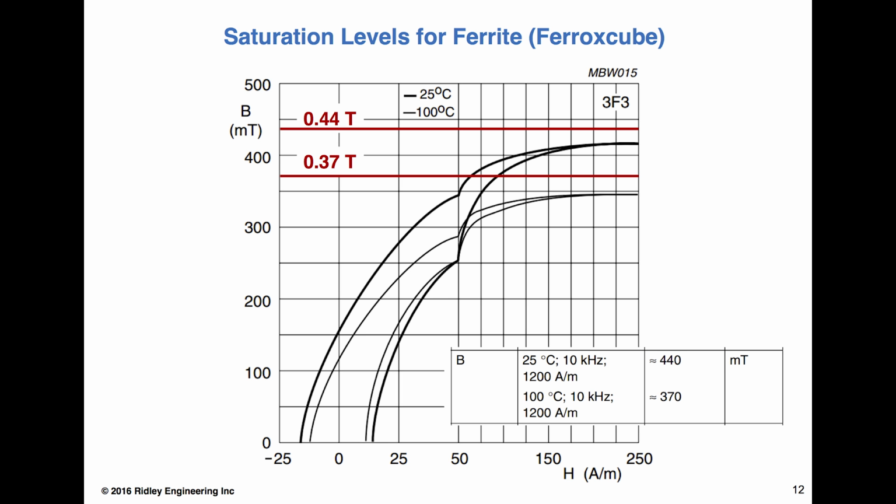A lot of the core loss papers you'll see get some very nice electronic-only processing to get core losses, but I'm not sure they're working with the very, very low-loss ferrites. Not completely up on this. I don't know how the core manufacturers are actually doing their measurements these days. Maybe they have the accuracy they need, but there you go.